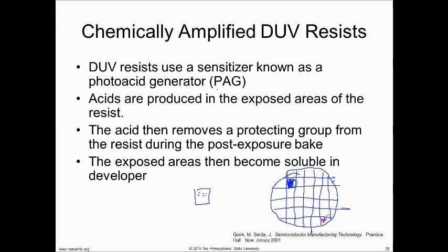I can't draw, so I pretend the colors help. But see this die down in here? That die wouldn't be completely aligned, and those chips would be bad. So it's hard to do this whole wafer at once with a big mask like this, with all my dies on there at once. And that's what I do in contact lithography. But in a stepper, I need the resolution to do things way submicron with perfection on every Pentium chip. So that's what a stepper is. I'm teaching you what a stepper is.